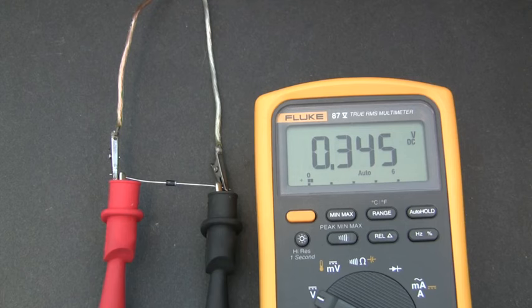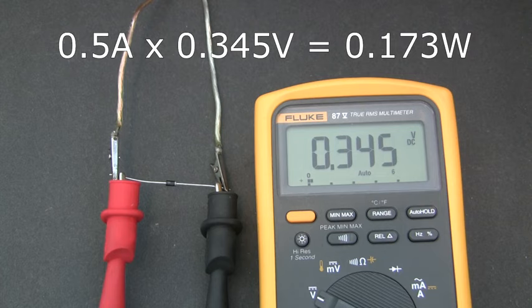Now let's try the same experiment with a 1N5817 Schottky diode. We've got the same 500 milliamps flowing through it, but the forward voltage drop is only 0.345 volts instead of 0.832 volts. 0.5 amps multiplied by 0.345 volts gives 173 milliwatts of heat instead of the 416 milliwatts we were getting with a silicon diode.